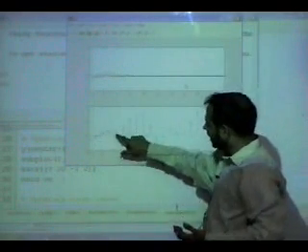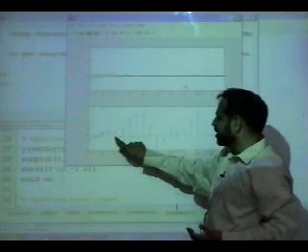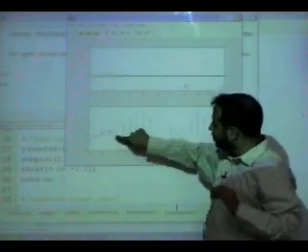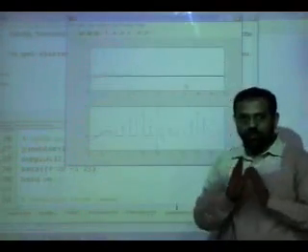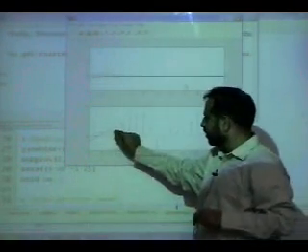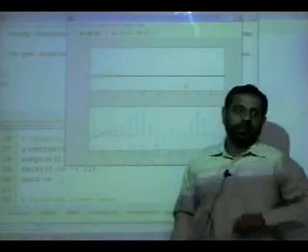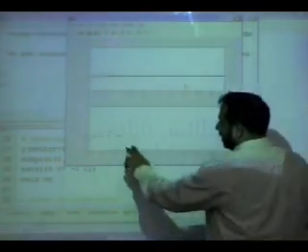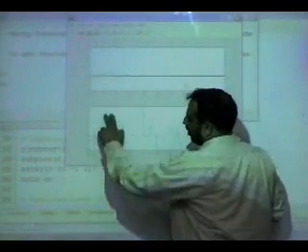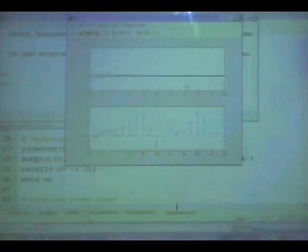Okay? Remember, every other sinc will pass through zero here until you get a sinc for this particular sample, only that sinc will have a non-zero value, which is exactly equal to the value of the sample. Okay, but then in between you have a lot of sincs which are just adding up to give you the shape of the signal.